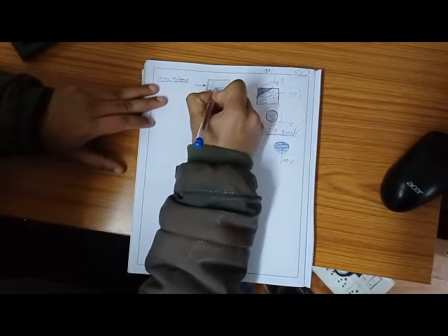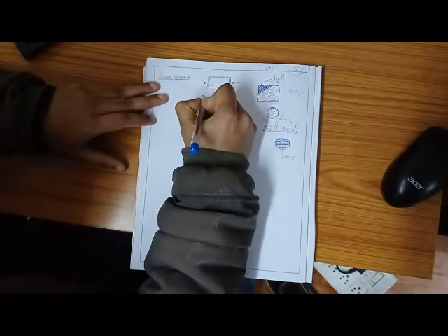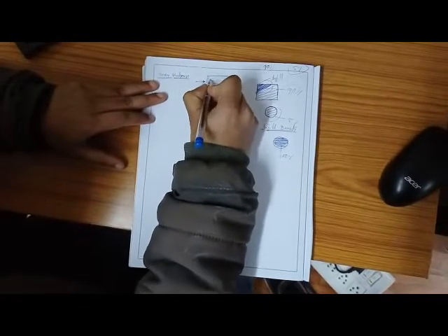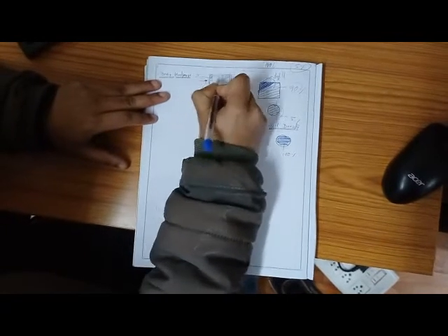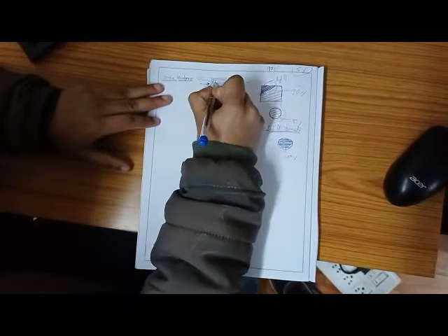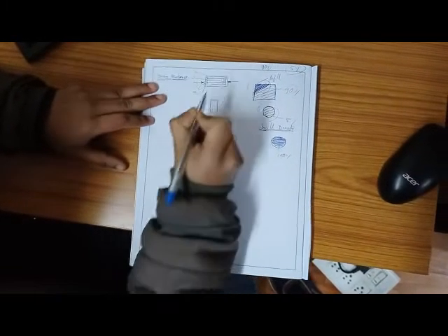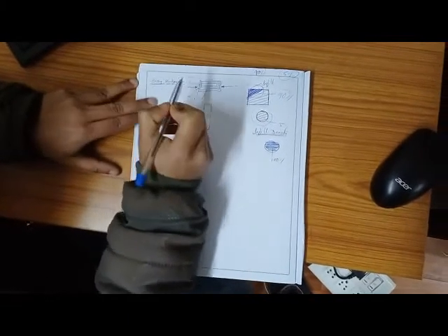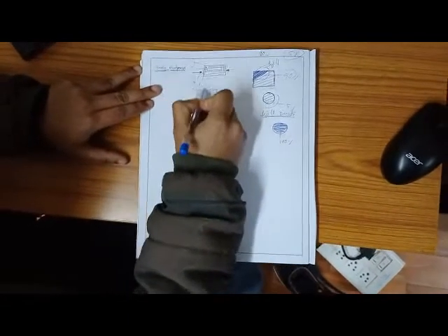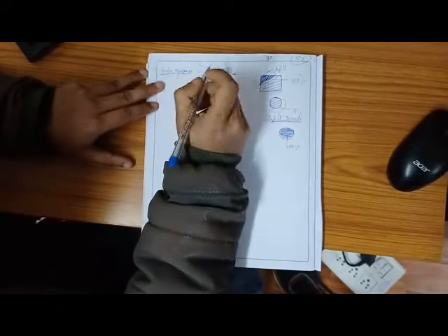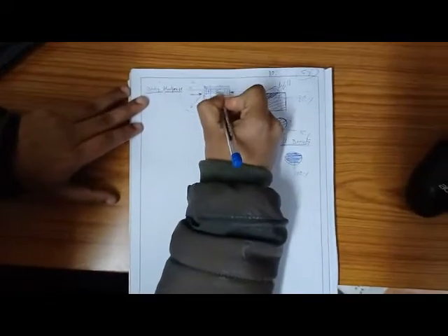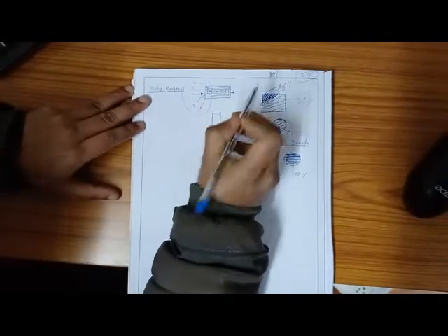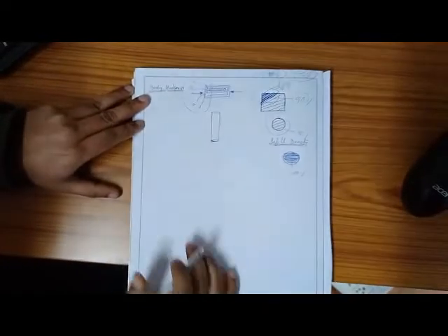This is the first boundary, this one is the second boundary. I'll make one more, this is the third boundary. Let's make a fourth boundary. We'll make 4 boundaries. This is called body thickness. So in total we have 4 boundaries or 4 rasters. It is also called raster, and after that it will start making the infill in this direction. This is called the body thickness.